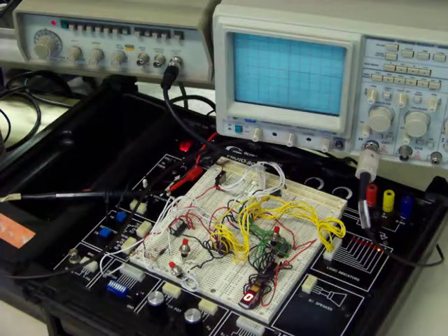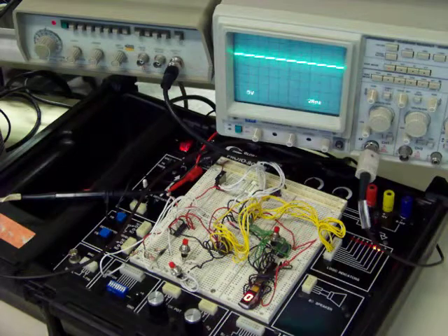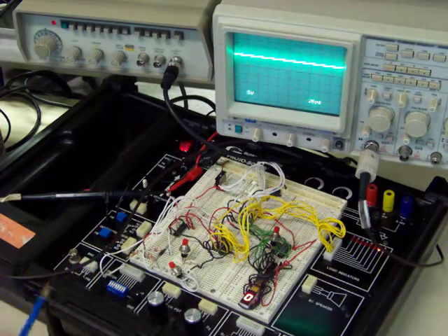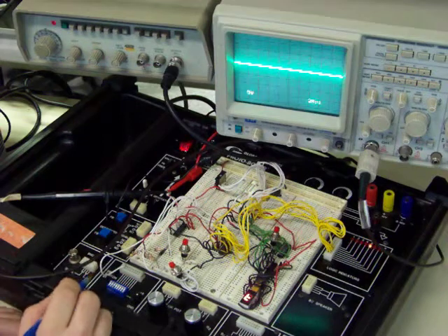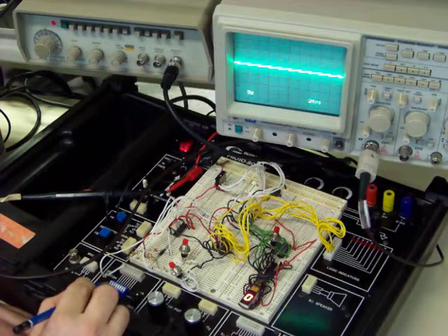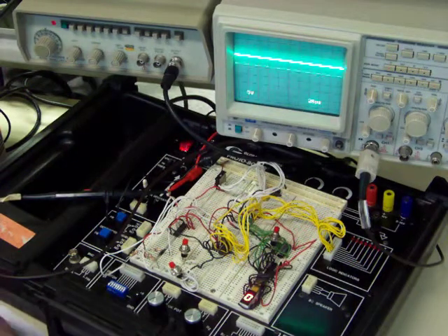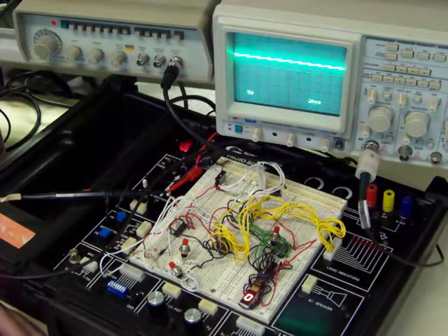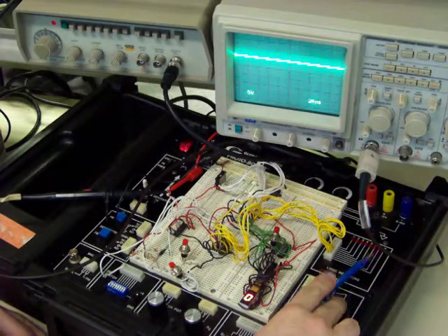When you first initialize the chip, you'll see it goes through and counts through in auto mode, showing the original garbage that's found in the chip. To enter the data in, we'll switch it into manual mode, and then we will enter the data at the address displayed on the LEDs.